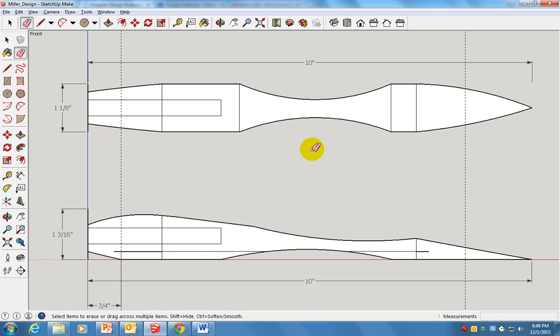So what we have now is a very, very nicely drawn piece here. And if I wanted to do some dimensioning, I could click here, and let's see if I can dimension between these. Is it going to let me do that? No, it's going to give me the radius. Make a liar out of me, of course. Well, T for tape measure, and you can actually see that's approximately 7/16. So that's how I would do that with that.